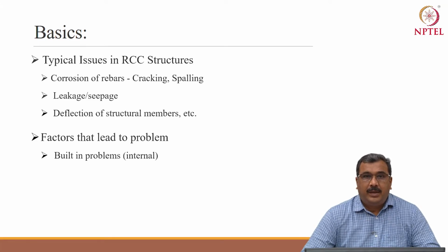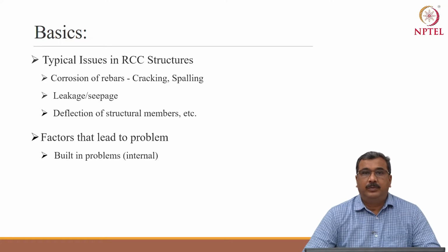If you are not selecting a sulfate resistant cement for an underground structure in a coastal area, then your below ground elements are not resistant to sulfate attacks. You will have a problem. If you are selecting a material considering durability and performance of the element, you may use slag cement in an adverse environmental condition. It's going to be helpful.